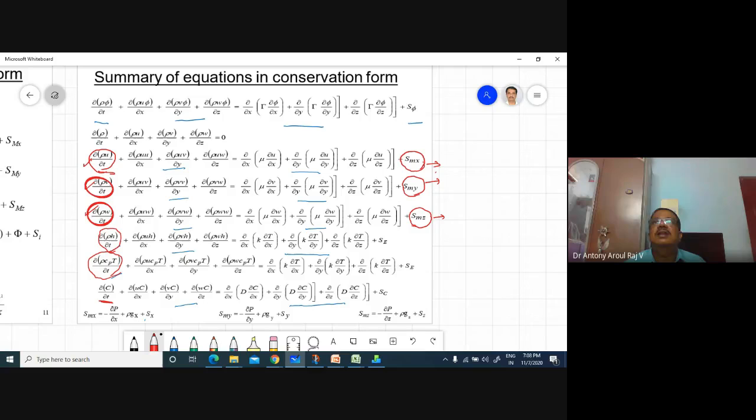So what is happening is that you can model the room, mesh it, and solve it. And whenever the flow is coming to that particular fan, the momentum fan portion or the fan domain, you are not going to mesh anything.